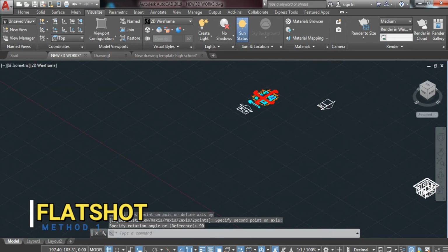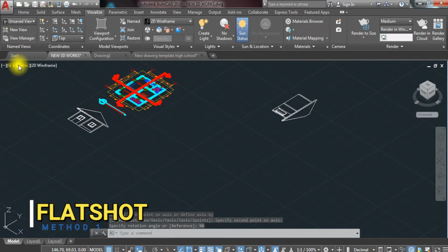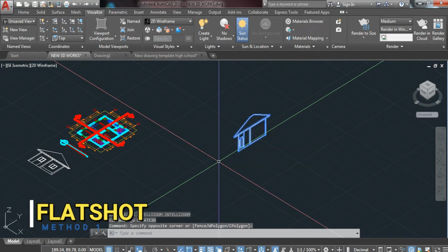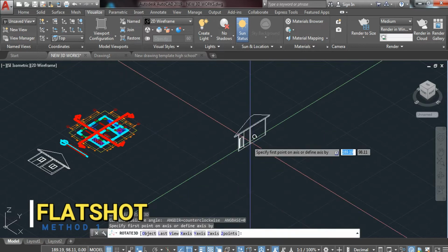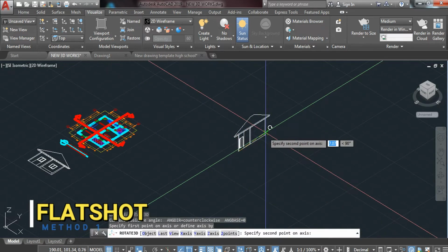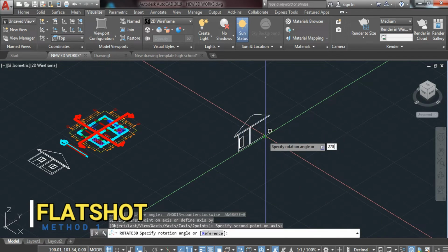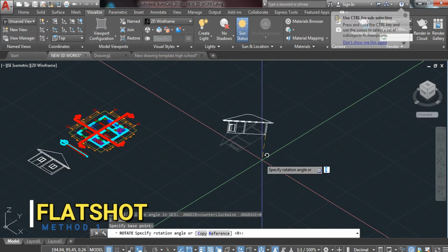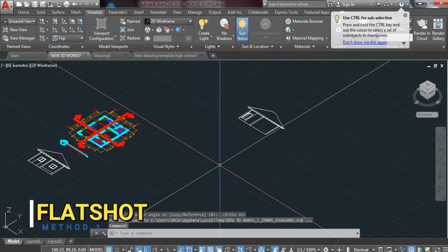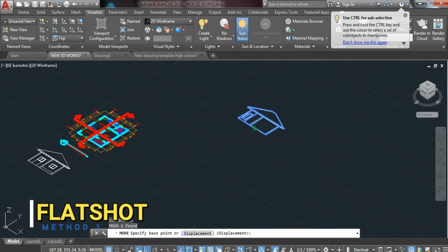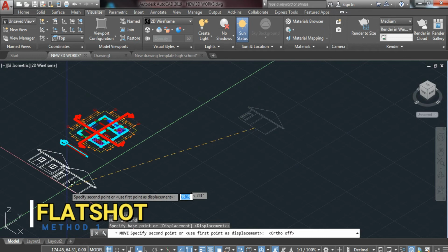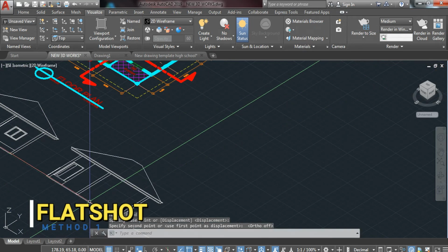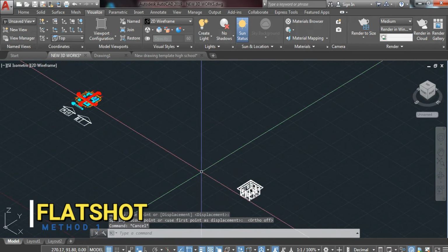So it's up to you, you can just rotate it in the most. Okay, so i-rotate na lang natin siya. Rotate 270. I'm going to change the angle from left to right. I'm going to say 270, and then rotate the object. F8, and then move this one right away on your front elevation. So somewhere here.